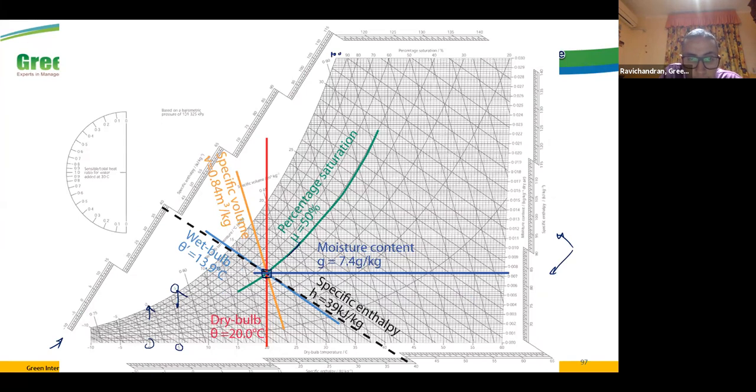To bring the value for enthalpy, we just bring a ruler. I put the edge of the ruler on the point for the requested energy here and rotate the ruler, until the value on this scale matches the value on the same scale on the other side. I rotate up and down, clockwise and anti-clockwise, until I reach, for example, a match between 39 and 39 kilojoule per kilogram.